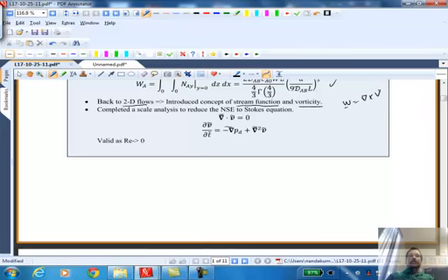Okay, and then we did a scale analysis to show under what condition we can still ignore the inertial term. That is, under low Reynolds number, the inertial term is not identically 0, but it gets multiplied by a small number, so we throw that out. And there is a large class of problems where this low Reynolds number flow is applicable. But the Navier-Stokes equation reduces to what we call the Stokes equation. So today we are going to set up a problem of solving this Stokes equation.